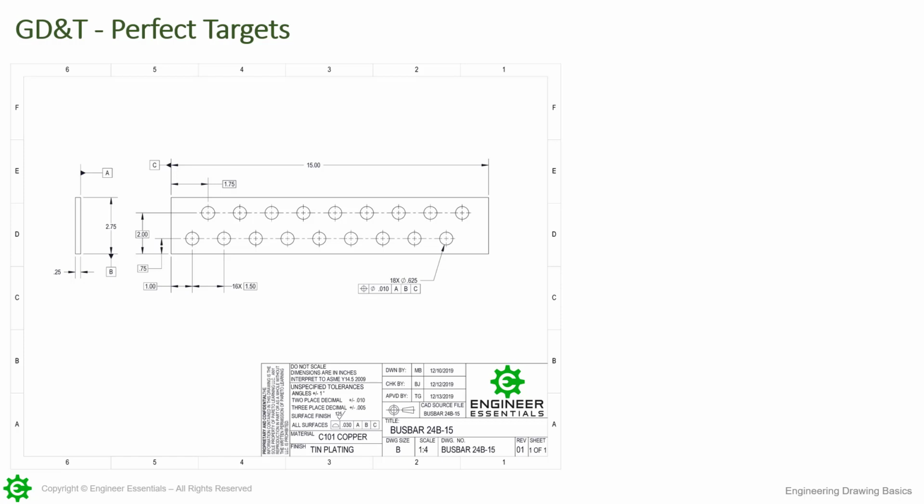They're using a position tolerance here, as you can see, for those 18 holes. There's a lot of options we can do with this here at this point, but just looking at it for what it is, they have the bottom surface. In this case, it'd be the top surface of third angle projection. So remember that. So on this one here, that bottom or top surface is A, primary datum. According to this, it's primary. And then B is right here.